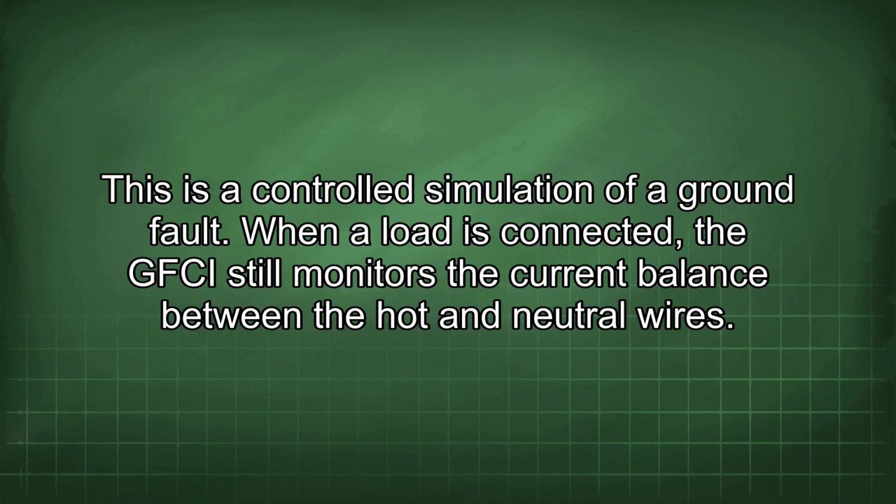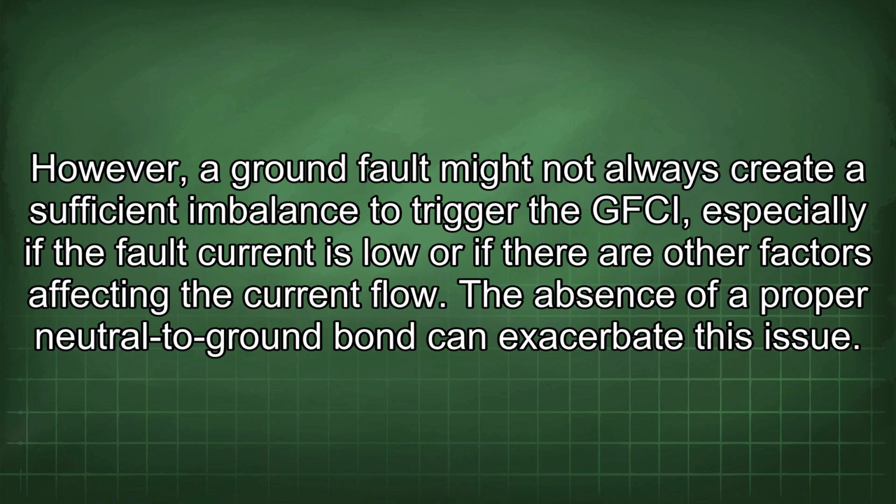When a load is connected, the GFCI still monitors the current balance between the hot and neutral wires. However, a ground fault might not always create a sufficient imbalance to trigger the GFCI, especially if the fault current is low or if there are other factors affecting the current flow. The absence of a proper neutral to ground bond can exacerbate this issue.